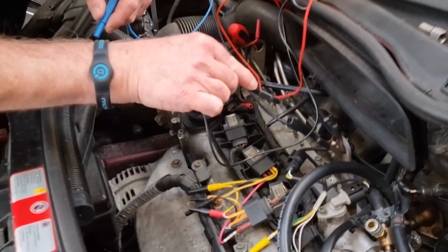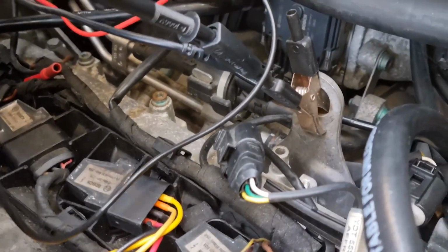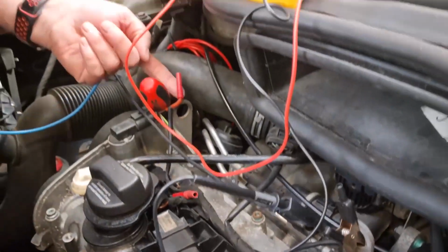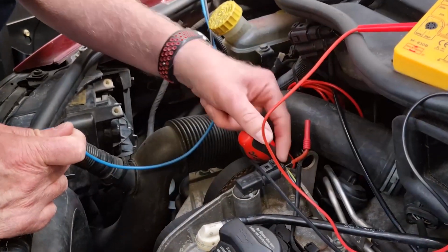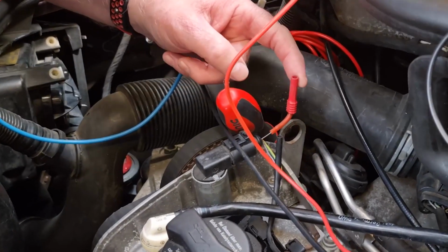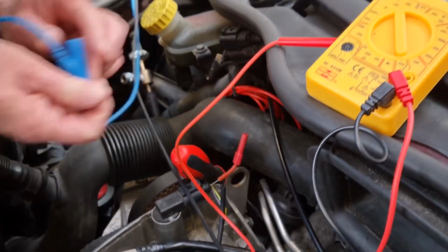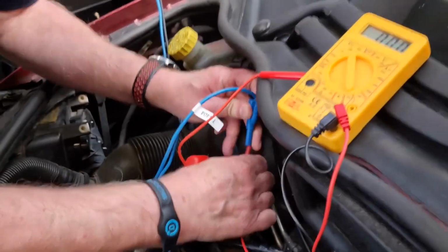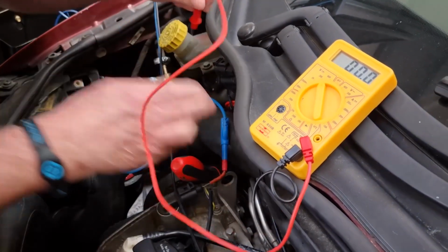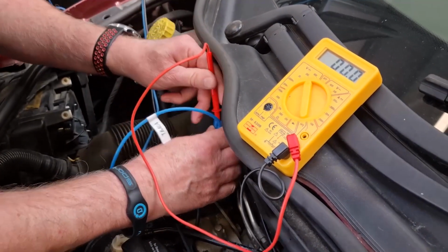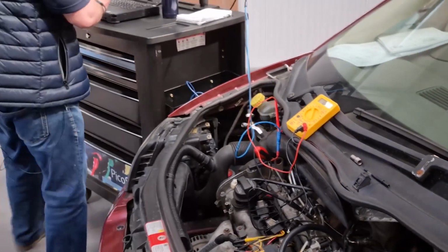So what I've got to do is plug in my multimeter, turn it on, and here we have our sensor. We've taken the protective cover off the back, and we've got one of our flexible backpinning probes pushed in there, and we're now going to plug in our test lead onto there, and we must just remember to plug in our voltmeter. So we're now going to come to our software.